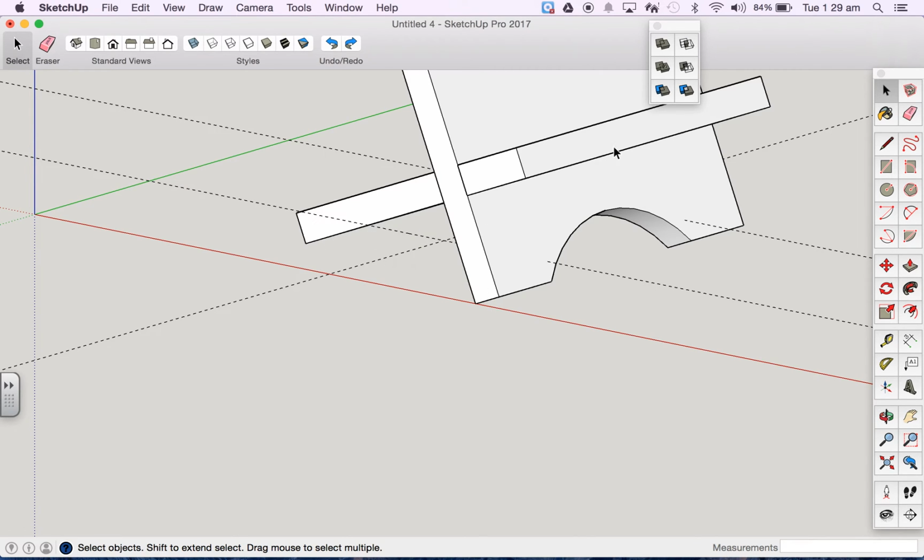So what we're going to do is use the solid tools now to modify this object so this bottom edge is flat. Now we could draw a line across from here to there, and it would push-pull until it got to this curved bit here, and that's where it'll all go wrong. It doesn't work very well. So a better method is to create another three-dimensional object which we use to cut through the drawing we've made and to level off the bottom of the legs. And I'll show you how that's done.